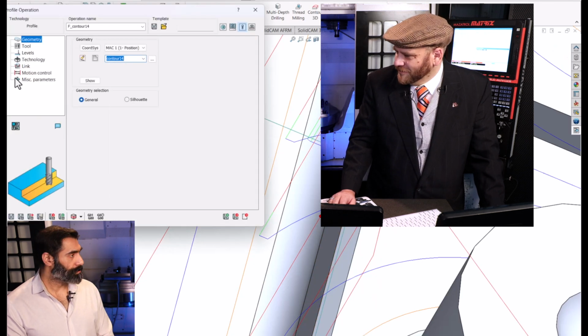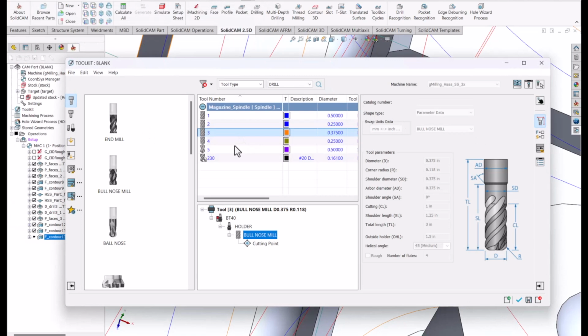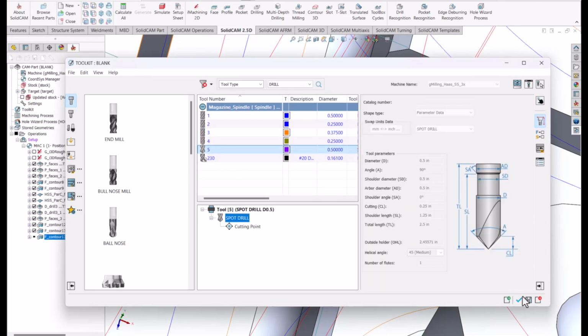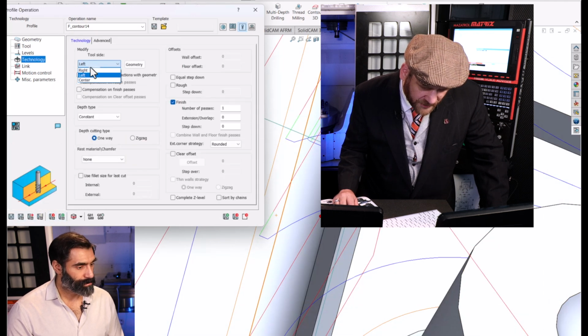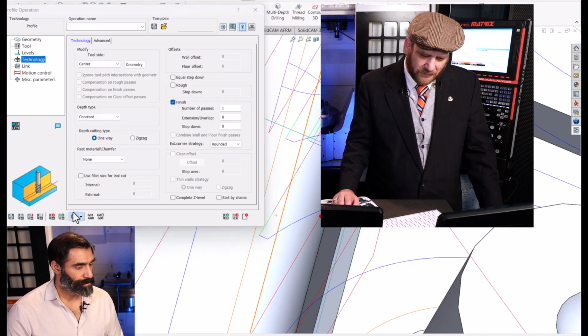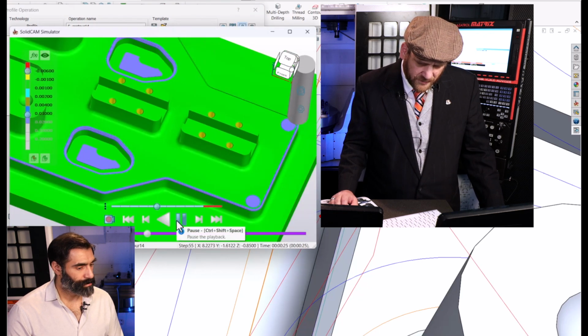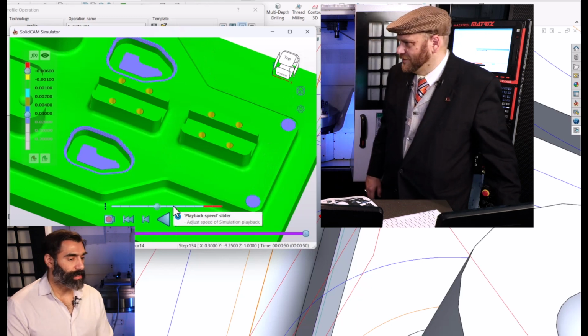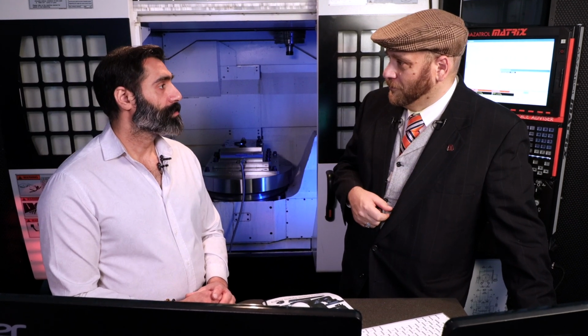It's plus minus 20. So plus minus 20 is not something I tend to worry about in modern machining. I'll just run right down the center there. And it'll take that model right off the chamfer and bring that right to size. Nice. So there you can see just a real basic overview of how I use MBD in SolidCAM and the advantages of being inside of SolidWorks in order to machine this.